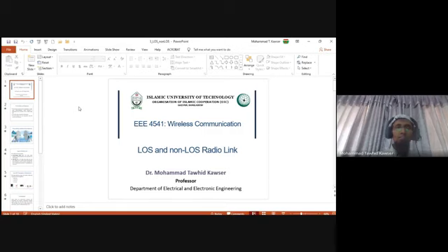Normally the signal attenuates in any kind of medium. When it attenuates to a very low level, you can no longer retrieve the information from the signal. So there is a particular length of the cable through which, considering some standard level of transmission power, you assume the power at the receiving end gives you how much loss, what percentage of loss of transmit power you have in the cable.